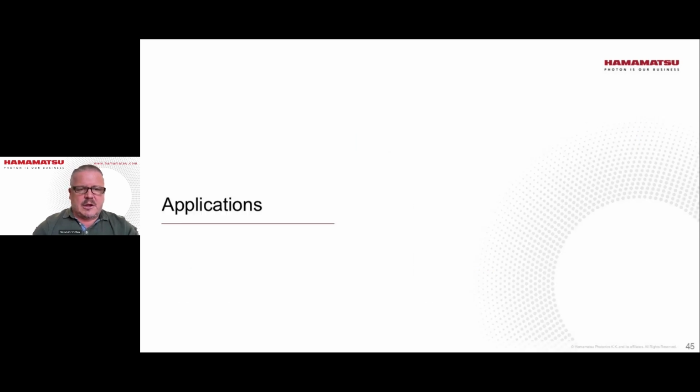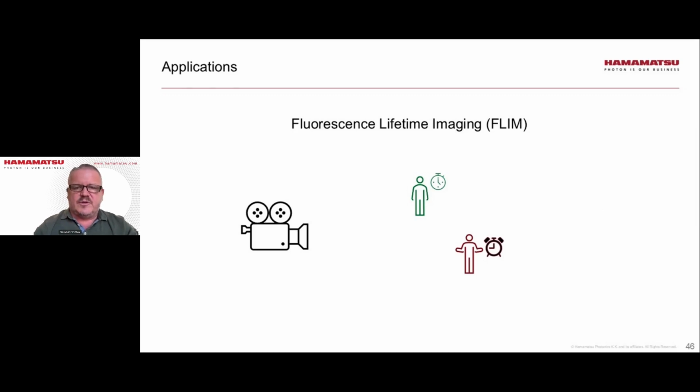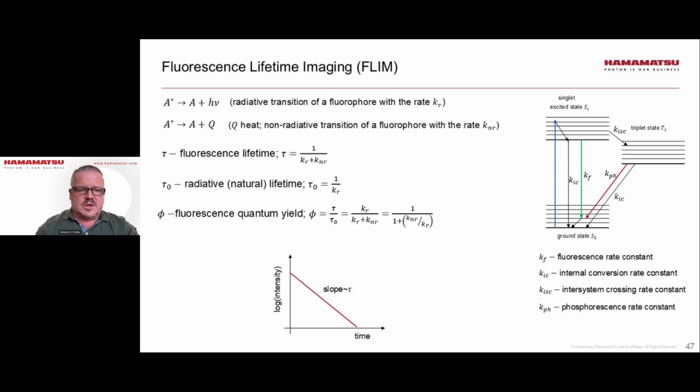So with this, I would like to now quickly go over some applications of SPAD, single elements, and SPAD arrays. Most of these applications will have one theme in common, which is the ability of a SPAD to timestamp events, something that other detectors cannot easily do. Remember, for imaging devices like CCD and CMOS, you can only tell arrival of photon to within the integration time. So I would like to begin this quick overview with fluorescence lifetime imaging.